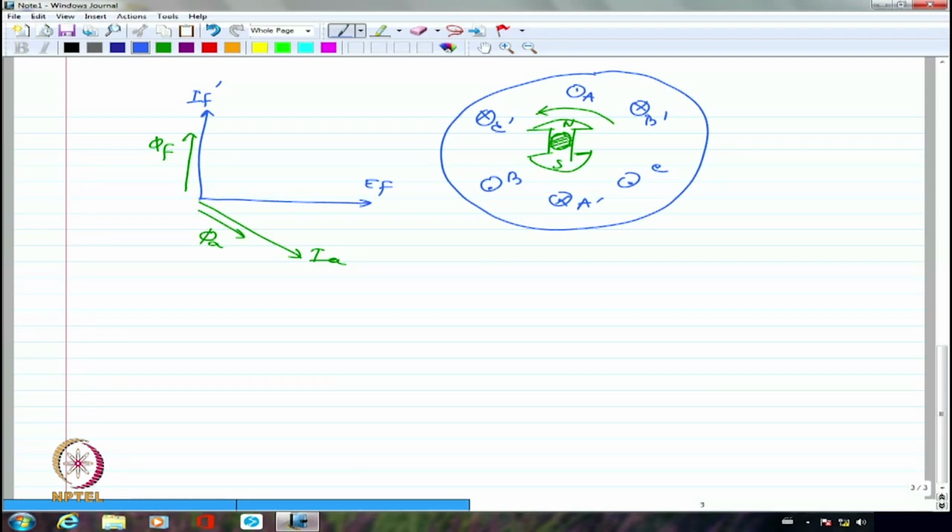The DC current definitely has zero frequency. It is not a rotating phasor. But I am looking at it from the viewpoint of the revolving magnetic field. That is the reason I am able to specify IF as a phasor, a rotating vector. I am able to mention it only because I am looking at this whole thing rotating at synchronous speed. So, although physically I am rotating the magnet, it is equivalent to electrically creating the revolving magnetic field.